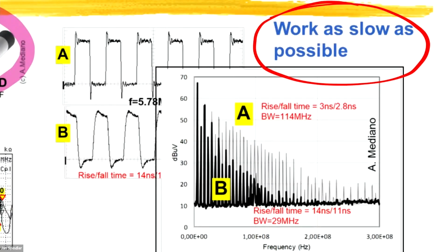You see the typical digital or square wave signal in electronics. If you increase the rise and the fall time, it's not so nice for digital people, no? Digital people want 0 and 1, 0 and 1, 0 and 1. But remember the sentence, marvelous things happen between the 0 and the 1. In EMI and in EMC, the important thing is the dI/dt and dV/dt.